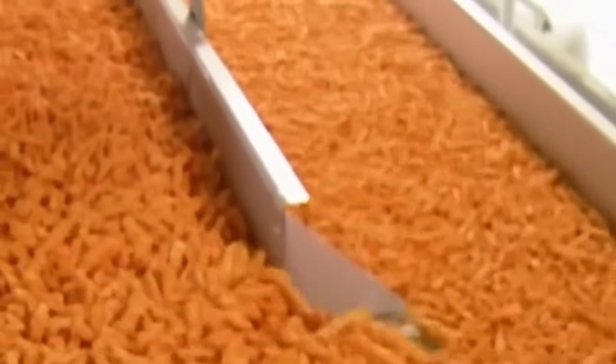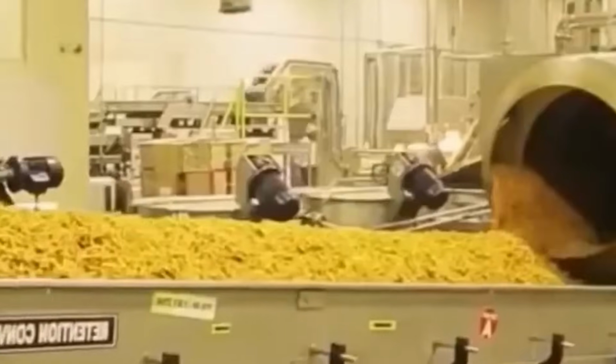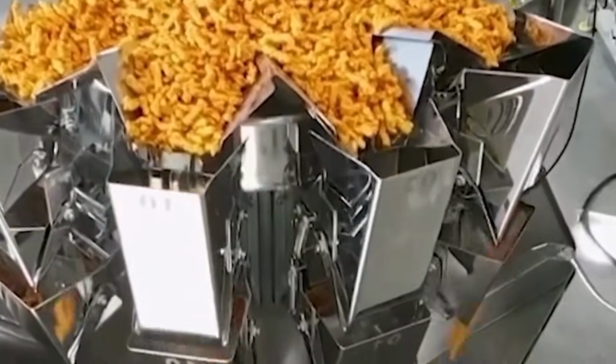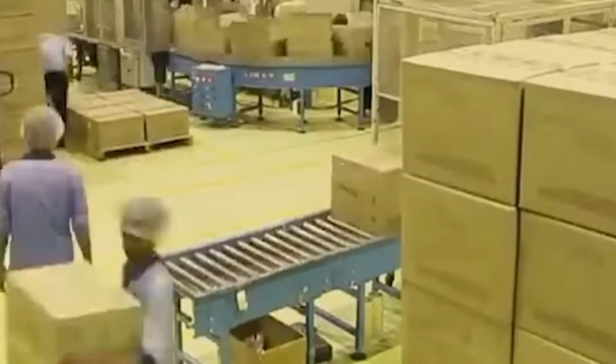Spray coverage is monitored using camera-based imaging systems that detect color uniformity across product samples. Seasoning overuse or underuse is automatically corrected by adjusting feeder rates or nozzle flow. Seasoned snacks are passed through a final cooling stage to ensure surface dryness and coating fixation. Cooled air is circulated over a vibratory conveyor bed, and product temperature is lowered to under 30 °C. The flow rate and cooling length are calibrated to prevent clumping in the packaging stage.